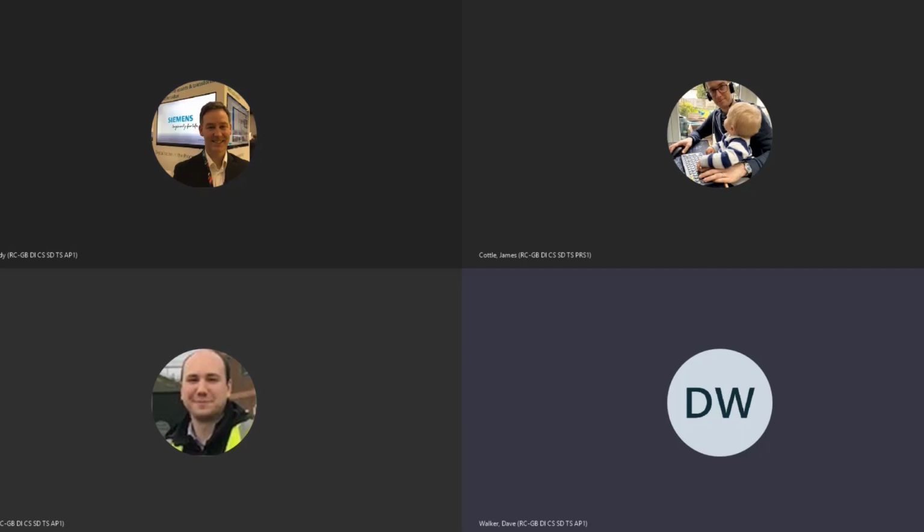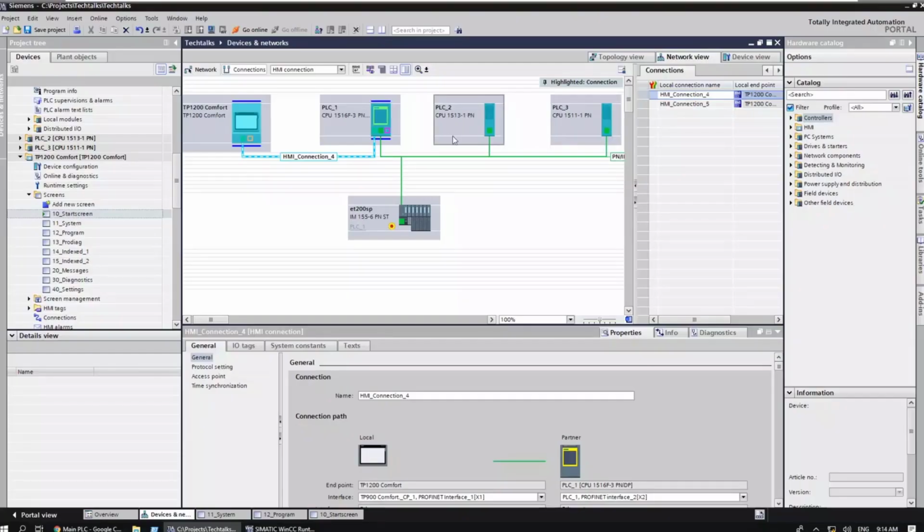So at the moment, you can see that these two PLCs are not on the same network. They're not on the same Ethernet network. If I highlight it, I've already formed up one routed connection. So the connection is actually routed through this PLC to there. So they are actually on separate IP addresses. The IP address of this is 10.15 and this is 0.13. So they are not on the same subnet IP-wise, but they can still talk to each other.